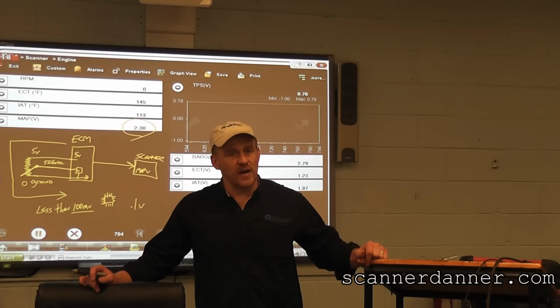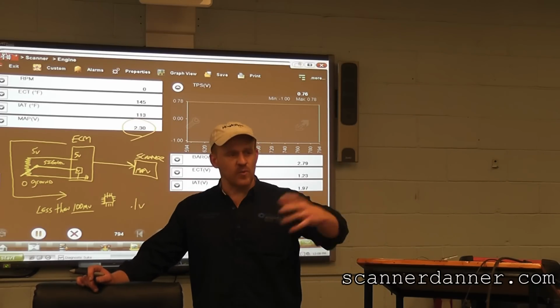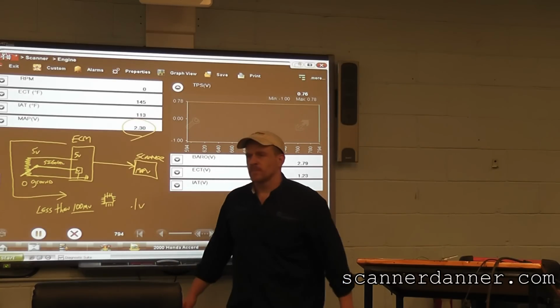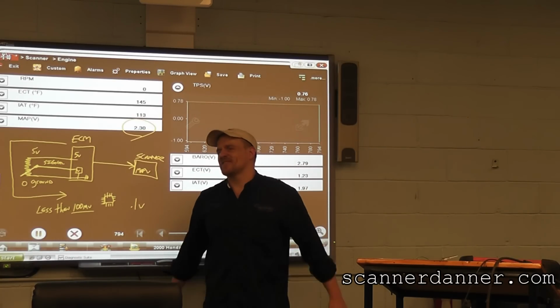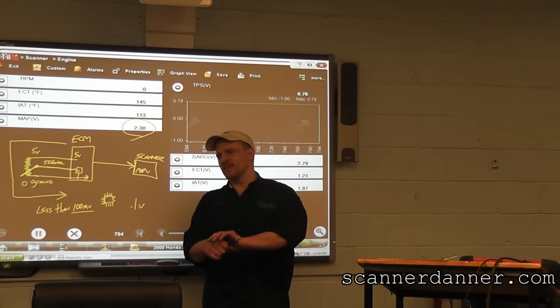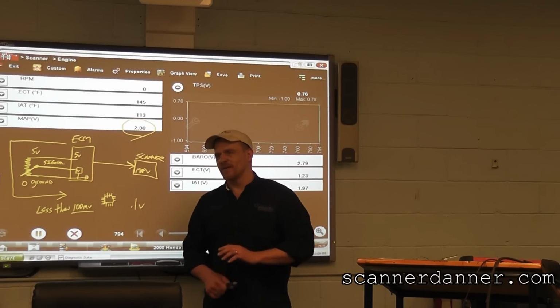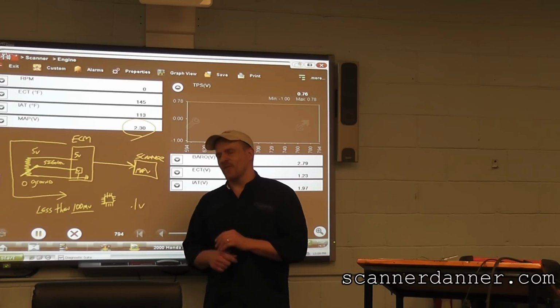When we check that ground, we want to be plugged in to check that ground. Loaded circuit, ground to ground. We'll get more into that. Have you found any exceptions to this through any manufacturer? Yes. Some sensors use a bias voltage on the ground, and voltage will be elevated intentionally to pull us off the noise of the block. It's called a floating ground. And we will need to talk about those too.